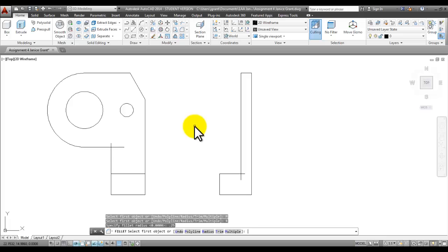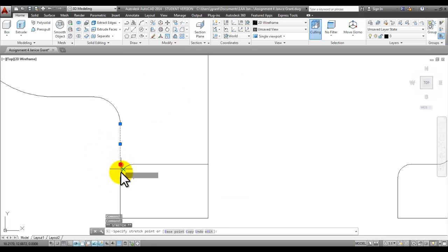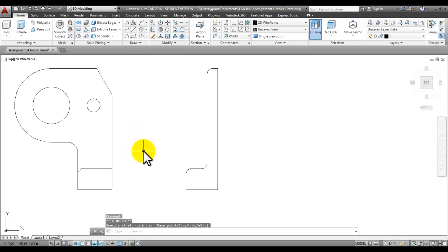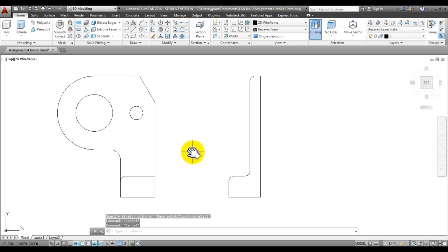And now, according to this detail in chapter 6, I'm going to click on these two corners. We have a fillet here, one at the top, and one here. Now, even when you're in the fillet command, once you start the multiple process and you've finished your fillets that you're working with, you can right click again and pick radius to change the radius to 0.5 and enter, so that you can stay in the fillet command to finish it up. And then I'll just extend this line a little bit using grips. I'm done with the 2D portion of the drawing.